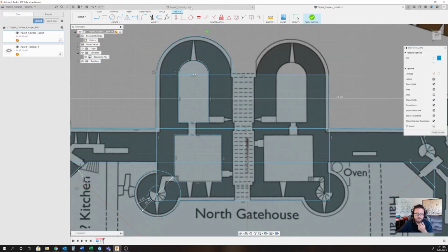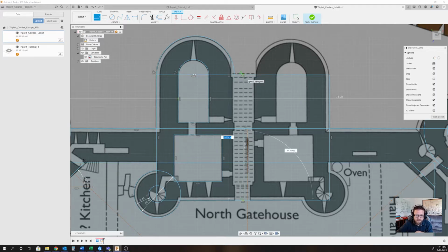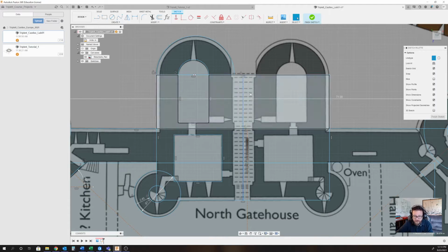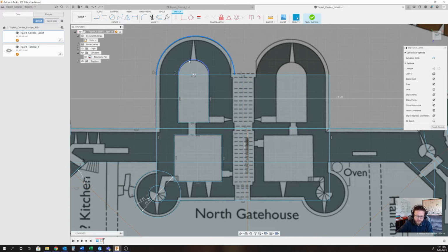So we can also create a mirror line here. I'm going to do that. Oh, I apologize. I hit escape on that just so I knew I had the wrong tool up. I shouldn't use a line for that. So right where this hits a triangle, you can see another little triangle icon. That's going to tell me I'm at the midpoint. I'll hit X. And now I can do the same kind of mirror operation.